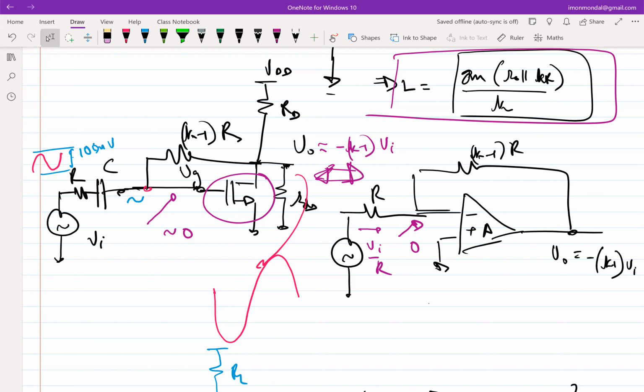Right? So if there is a high impedance node, if I inject a current somewhere, it should create a lot of voltage swing. If I inject any current in the loop, it should generate a lot of voltage swing at that node, right? Then only I can say this is a high impedance node. Does that statement make sense? Impedance is V by I. If I inject I, then output should be V times the impedance. If the impedance is high, then for a small current injection, I should get large voltage excursion, right?